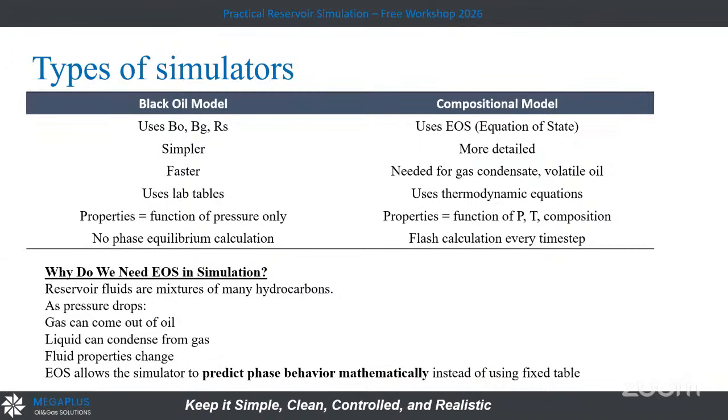with pressure. As an example, if we are dealing with a gas condensate, at reservoir pressure of 4,000 and the dew point of this fluid maybe at 3,000, you'll find the methane component will be much higher. But if we reduce the pressure to 3,000, the first dew or first condensation will happen, and you will see that the components of methane or ethane will decrease, and the mole percent of the C7 plus will increase.